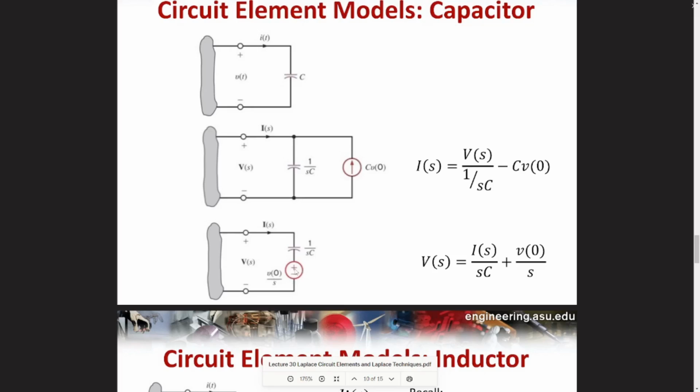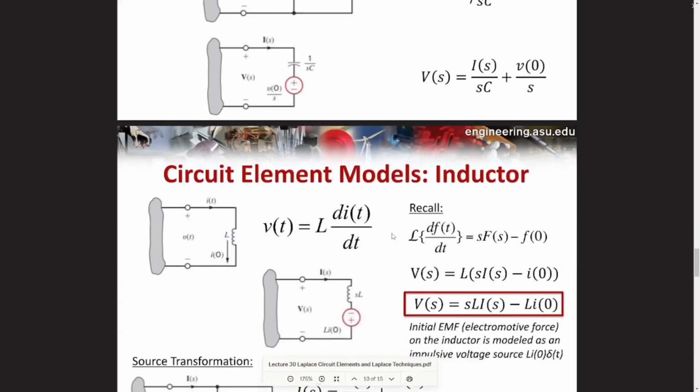So when it's written as a voltage, it's V of 0 over S, of course. In current form, it's coming from C dV/dt, and so there's a C V of 0 as a result of its calculation. So it matters which one you're using to determine which of these two expressions needs to go into place. That's the other thing to keep track of.